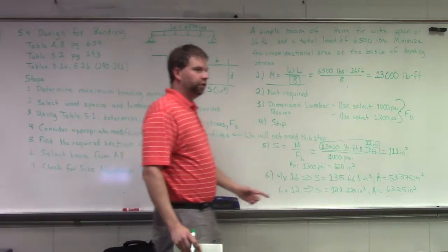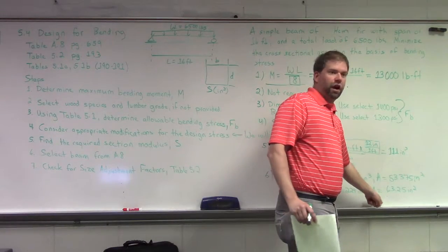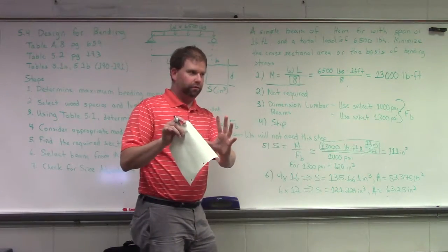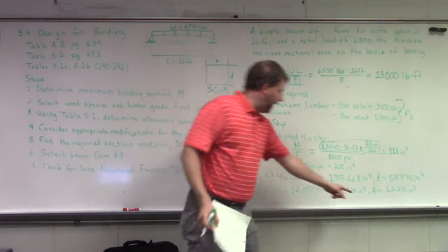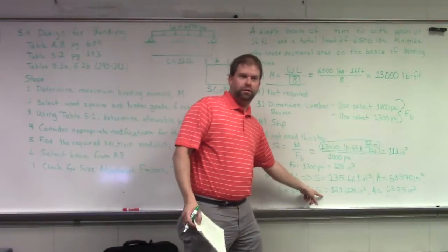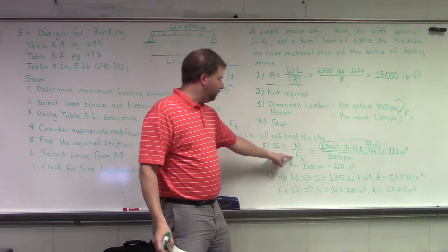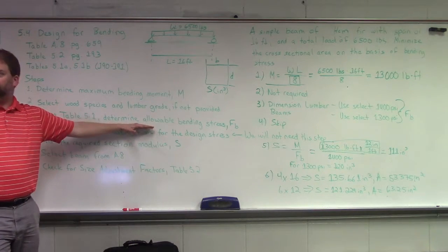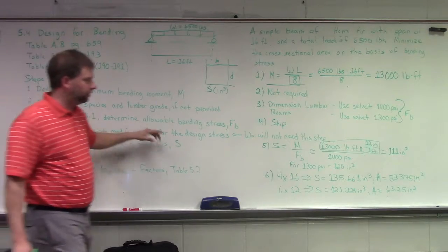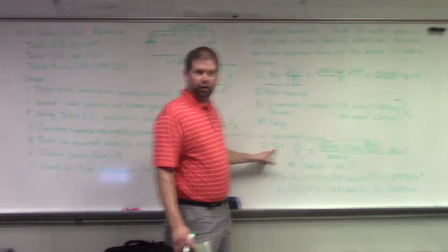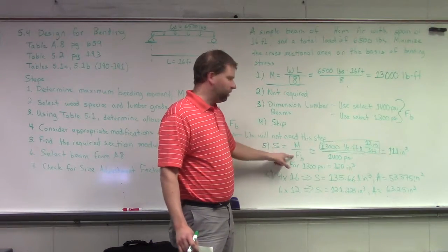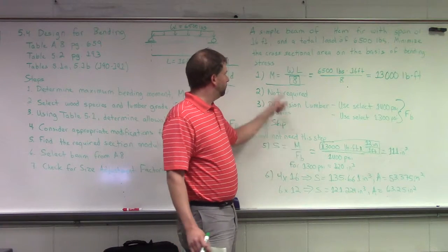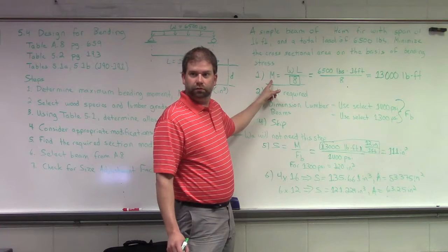Because you'll know your cross-sectional area, that's what you have to fit the thing into. You can use that to generate an S equation. You can figure out what your allowable bending stress is for the type of material that you want to use. Multiply your section modulus by your bending stress. That'll give you your moment.